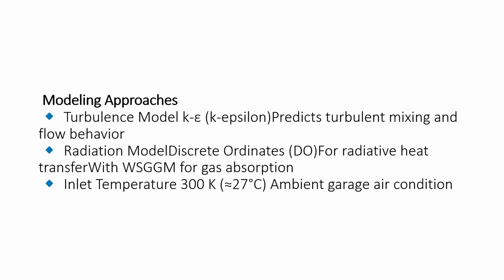Inlet temperature: 300 K. This sets the initial ambient temperature of the garage, which is about 27 degrees Celsius, representing normal environmental conditions before the fire develops. These conditions give us a realistic and detailed simulation environment to study the spread of heat and smoke, and how ventilation affects fire dynamics.